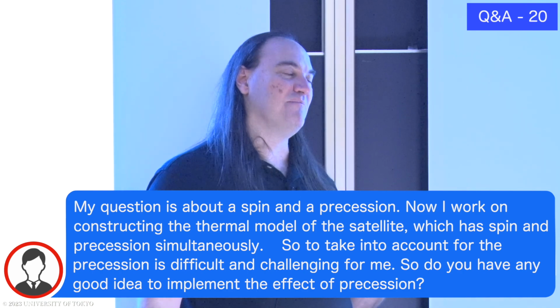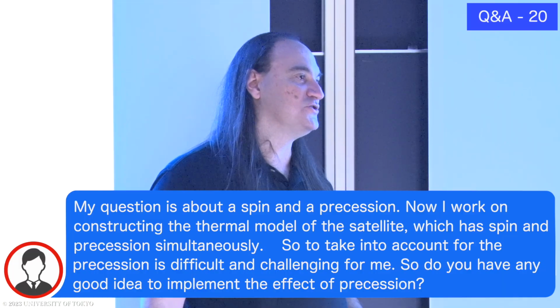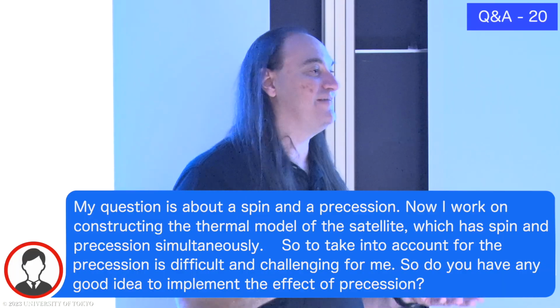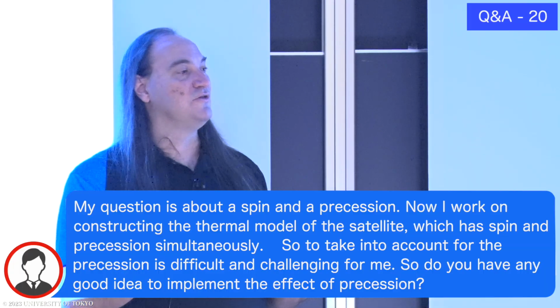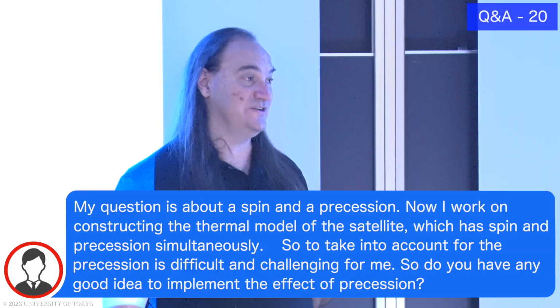And that came from years ago. We were at S-Tech testing a satellite, and the data collection system was every 2 minutes, and the satellite was rotating 1 revolution per minute. So we always got the exact same flux there, and we were wondering why the steady state numbers didn't match up. So think about the cadence that you're solving and the cadence that you're rotating to make sure that you're not always solving the same orientation.